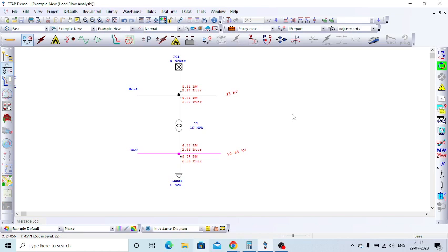Similarly, real power and frequency are directly proportional. So in order to improve the voltage from 10.65 kV to 11 kV, we have to use the capacitor bank to supply the reactive power so that the voltage can be improved.